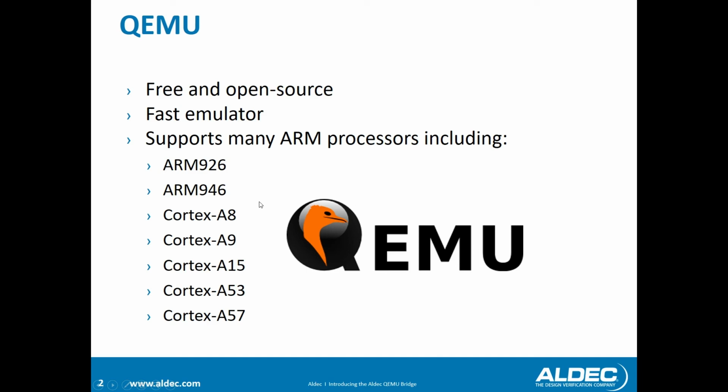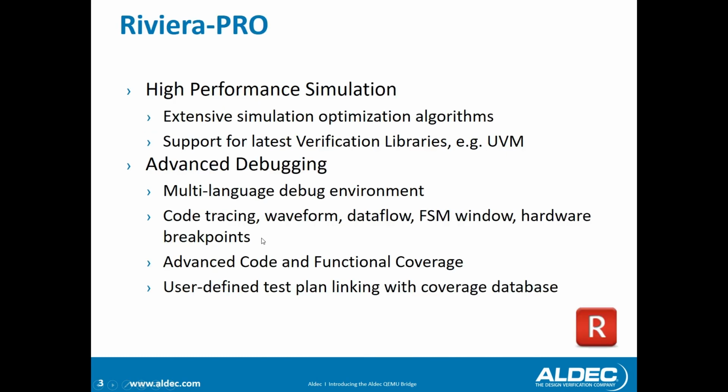In fact, that is what I'll be showing today, as QEMU will be used to emulate the ARM Cortex-A9 within the context of this demonstration, and will thus act as the virtual processing system of my Zynq-based design. Now, the design itself is just a simple PWM IP, which will be run as RTL within programmable logic. To simulate this component, we will be using Riviera-PRO.